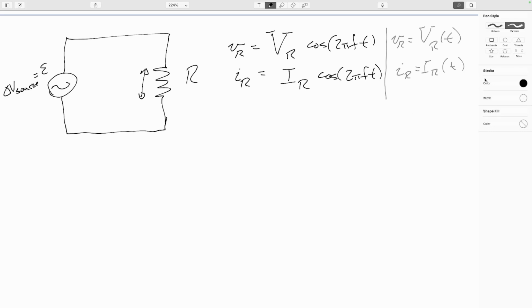All right, so we can go ahead and use Kirchhoff's loop law here and say that the EMF as a function of time, so we go through, we change by the EMF minus the current as a function of time times R equals 0. And we could say that that's the voltage across the resistor. Either way. All right, so what this means is that our current, since this is going as a cosine, will have both plus and minus signs. This means that our charges just keep sloshing back and forth through the resistor. They never really move very far at all.